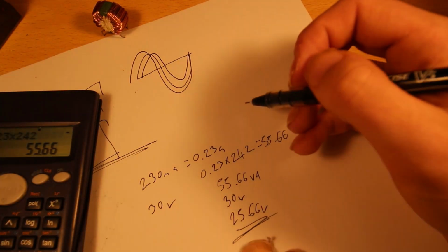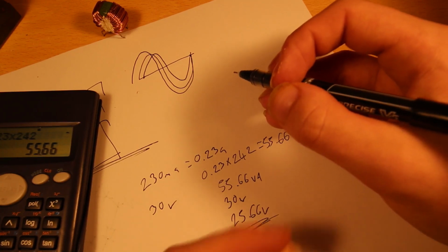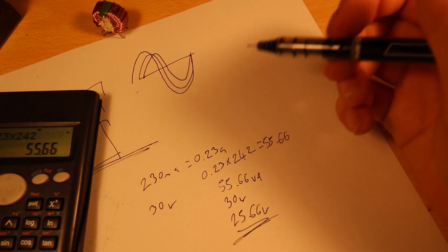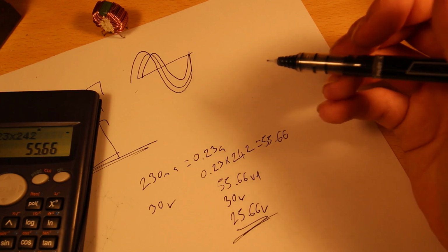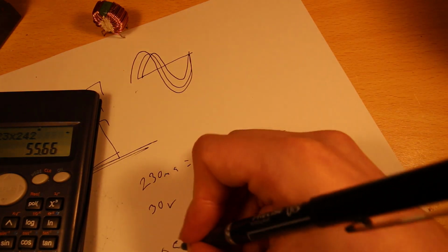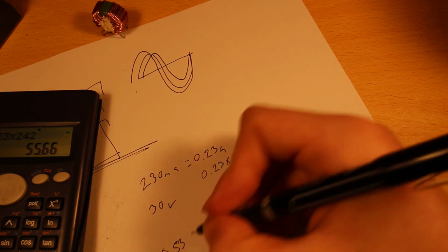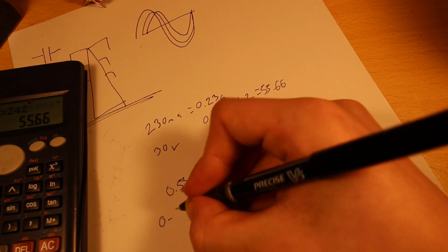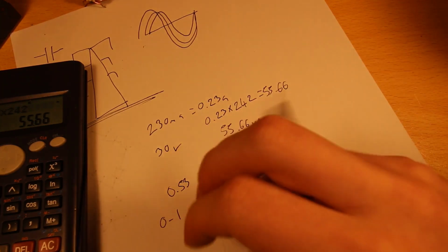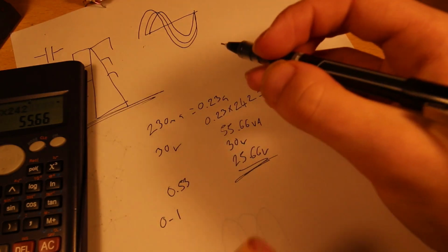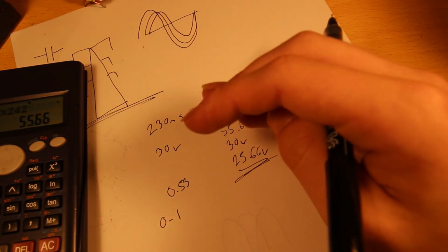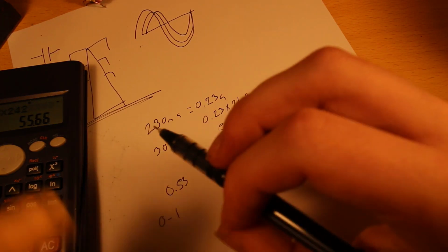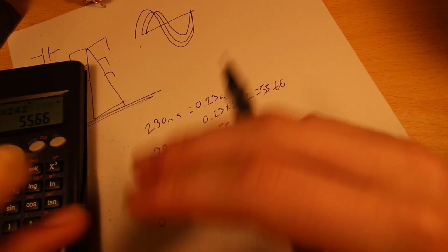And with DC, this doesn't happen. With DC, because the power can't be out of phase, you can't have these kinds of losses. The power factor of that is 0.53, according to my meter there, which is pretty terrible. Power factor ranges from 0 to 1, with 1 being what's known as unity, where they're perfectly in phase with each other, and 0 is where they're 90 degrees out of phase. A power factor of 0 is impossible. Well, physically it's impossible because you always will have a capacitance from the cable.